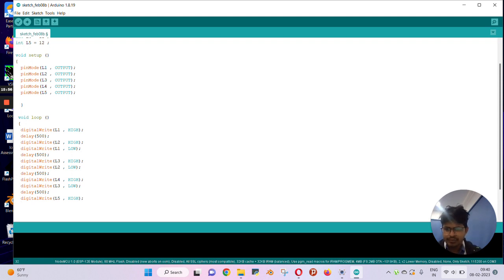Along with this, we have to make LED number 4 low. So we will write a command for that. After that, we have to give a command for 500 millisecond delay.